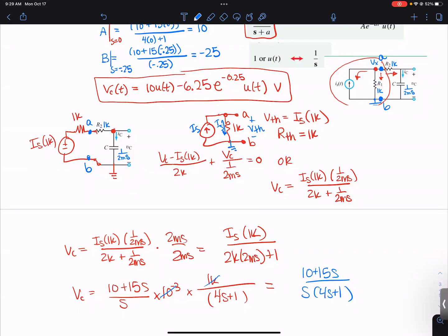Oh. And I just replace it with the voltage source and the resistor between A and B. So that's what I did wrong. I keep forgetting to add that extra resistance, that R1 on there. I just had the R2 value. Yeah, that's really important. This is your RTH and VTH.